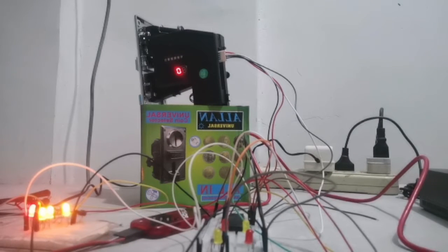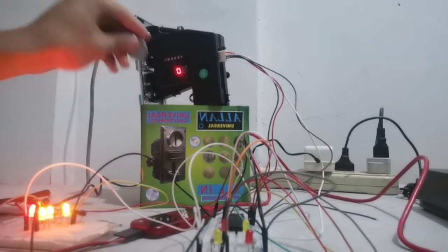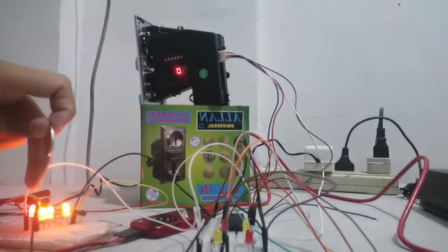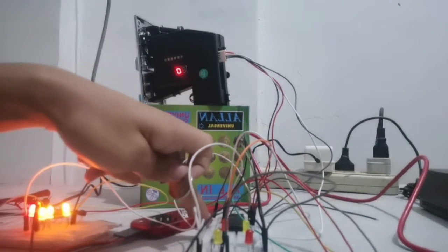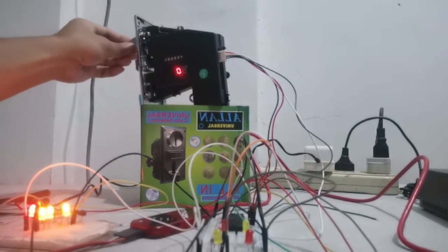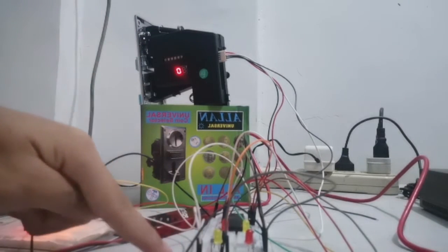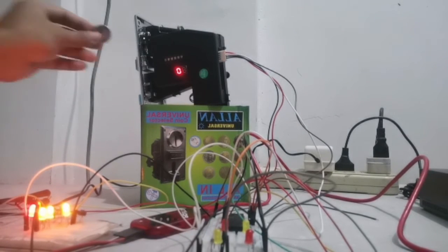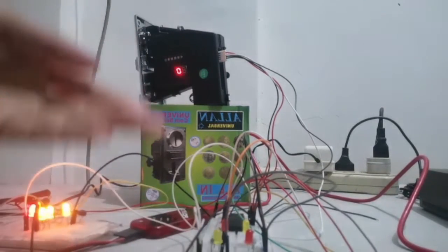Okay, so inserting our 1 peso coin here. The moment I insert this, this will change into A1, and you will see that the power source will blink because it indicates that a pulse has been through our board here. So 1, 2, 3, off. Okay, so as you can see, when I inserted the 1 peso coin, once again, the LED turns on for 3 seconds, 2, 3, and then turns off.